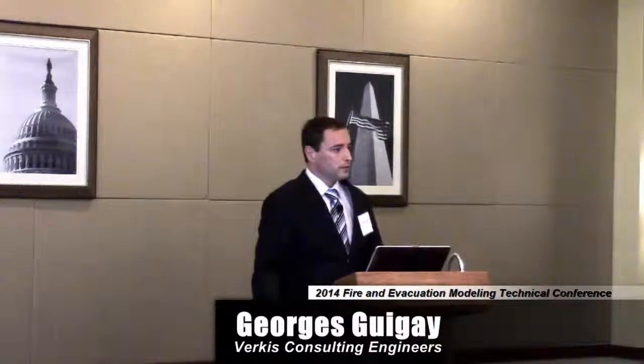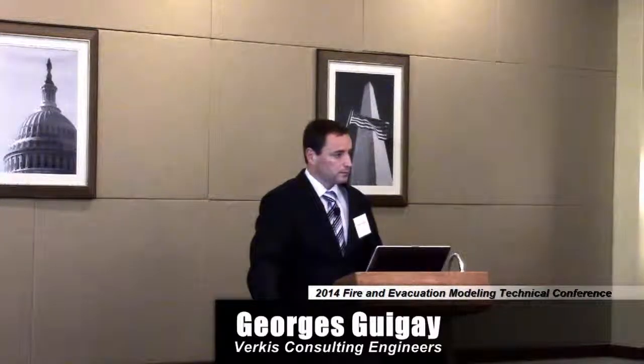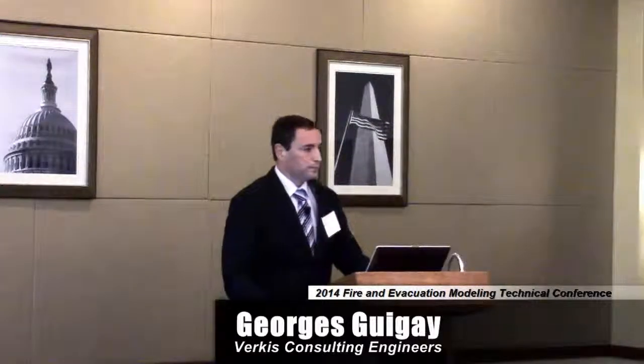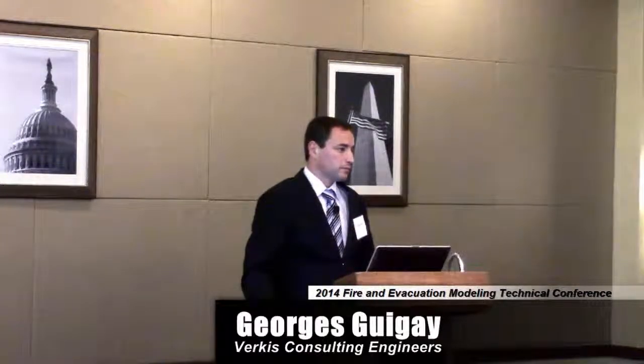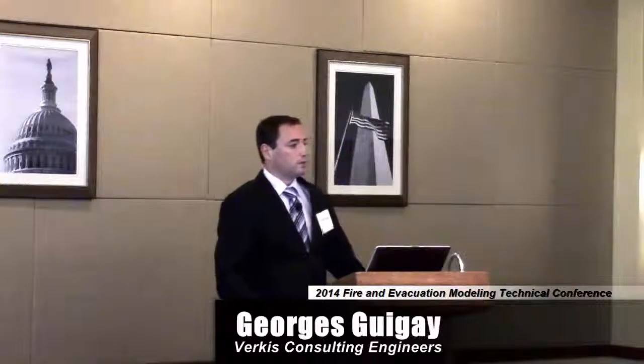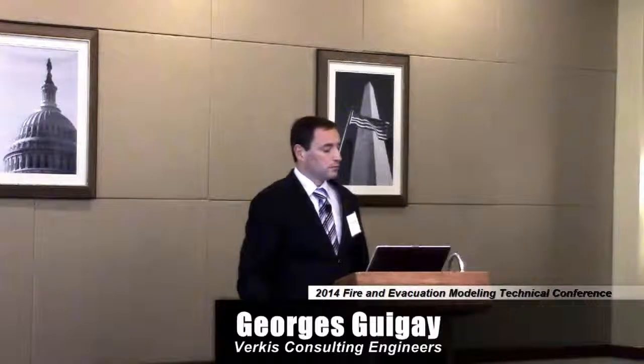Hi, I have a question, and it might be more for Kevin and NIST as well. Quite often when we do the ASET, we look at visibility. And you say that FDS6 is more conservative for what you saw. Obviously with changes in the models, there's going to be changes in how things are outputted. Without using the soot deposition, some of my colleagues have done some comparisons in the middle of a design for FDS5 and FDS6. They've actually found that visibility has been less conservative for FDS6. It's changed, and it's now actually showing that visibility lasts longer in FDS6.